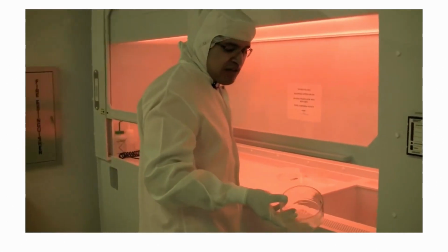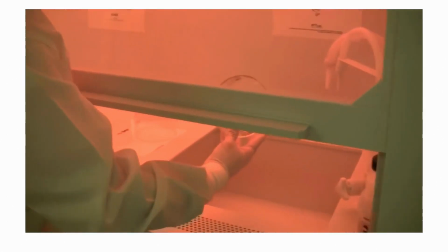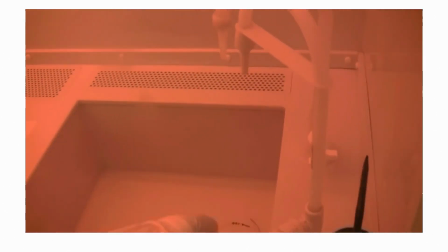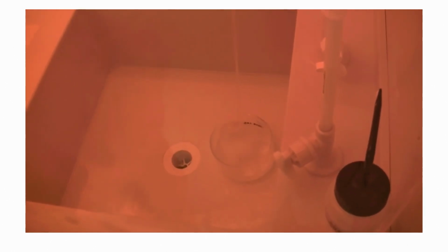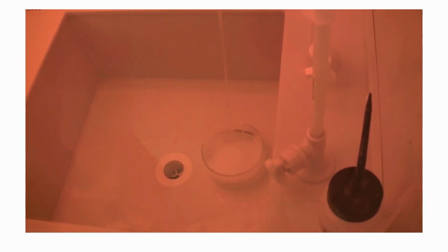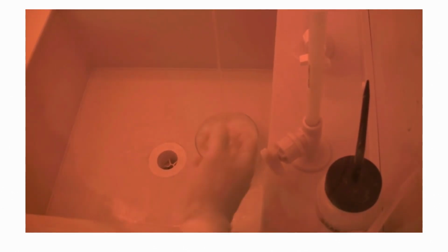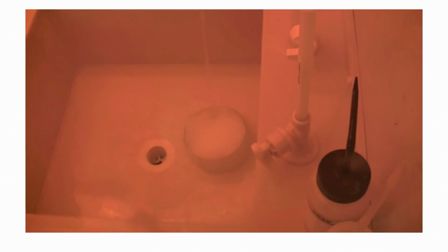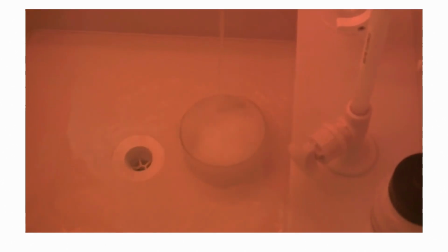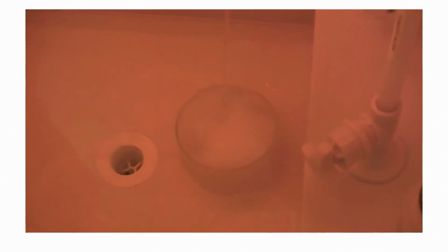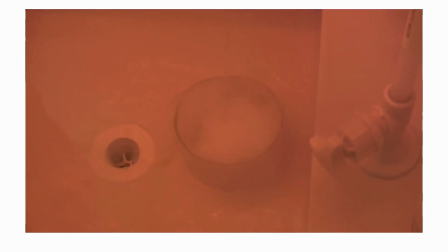Next, we usually rinse these. So what you can do is put this in the sink and run some DI water in it. You see it's a little soapy. That's normal. You keep rinsing it until the soapiness goes away. I'm going to speed it up a little. As with all things done in the clean room, you want to take your time. So you don't want to rush this. Just let it run. Go put away samples, things like that. So you see some bubbles, but it doesn't look soapy anymore, which means it's pretty much rinsed off.